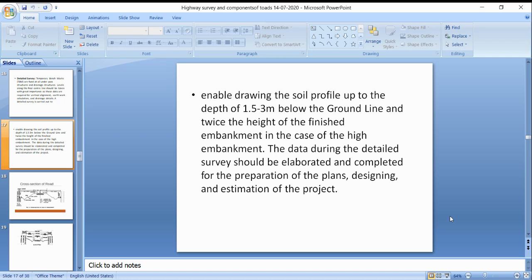In the longitudinal sections we will see the vertical scale, enlarged 10 times the longitudinal scale. So in the longitudinal sections, we are giving the longitudinal scale of the ground, and the vertical scale.